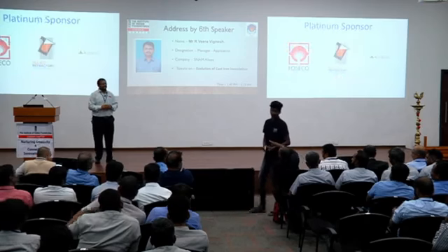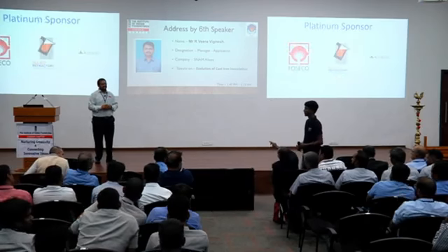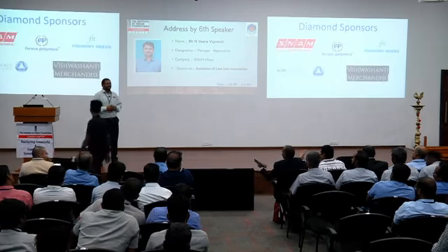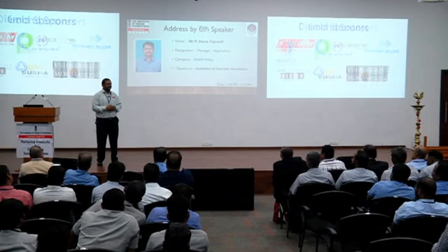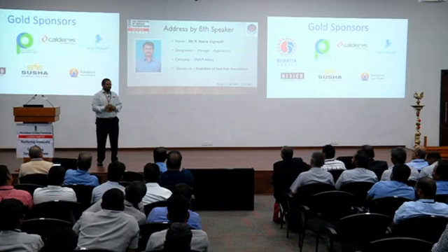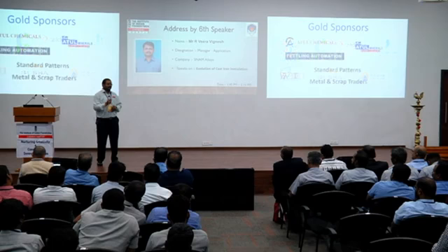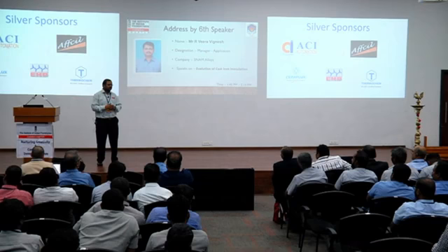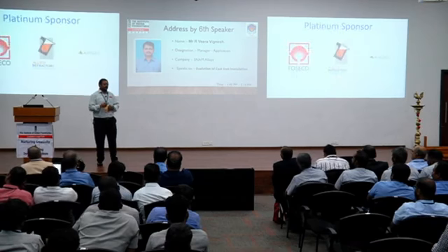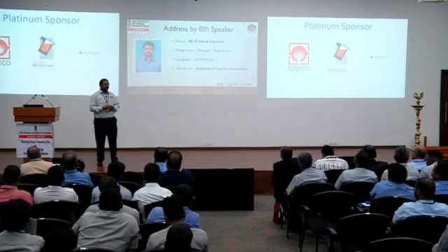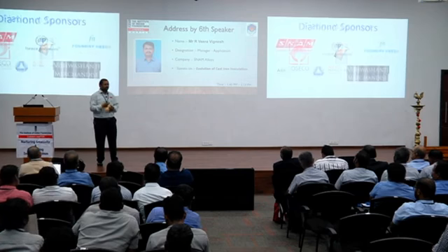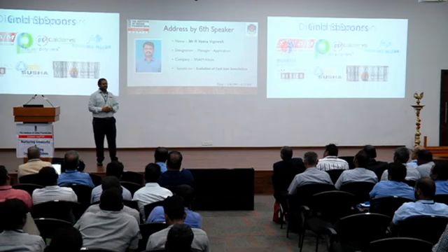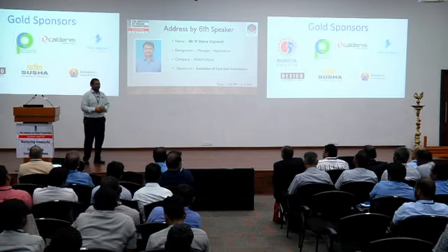What is the qualification method for inoculant or the measurement of the nucleation potential? Sir, no change in your defect or rejection percentage, sir. With respect to the same property which you are measuring, no reduction in your rejection percentage related to metallurgical factors, not pouring defects, sir. Say if your carbide percentage comes down, your steadite percentage comes down, or your type D percentage comes down, or your uniformity nodule count increases, then those are the measures of inoculation, after the production.